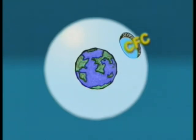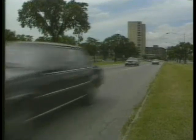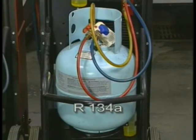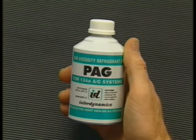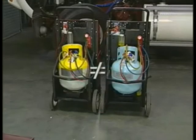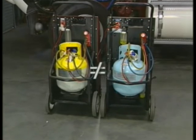Beginning in 1994, automobile manufacturers began phasing out the use of R12. By 1996, all vehicles sold in the United States were equipped with a new refrigerant called R134A. R134A has many of the same properties as R12, but is not detrimental to the ozone layer. R134A systems require the use of a different lubricant called a PAG oil. PAG oils vary by system manufacturers. Refrigerants R12 and R134A must never be mixed, as the refrigerants and their lubricants are not compatible.